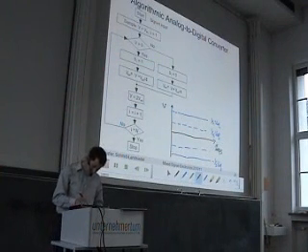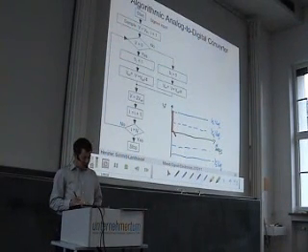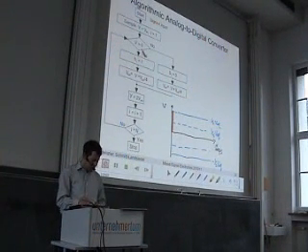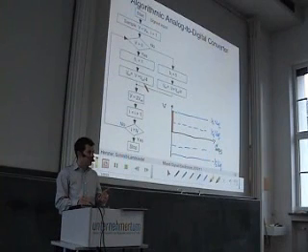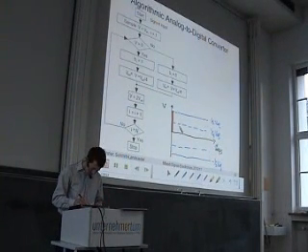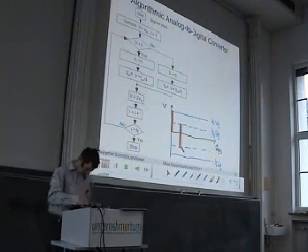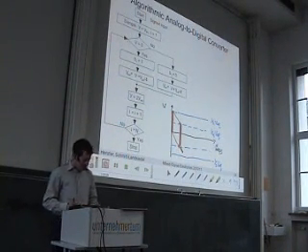Okay. All voltages that are in this range, for these voltages, we are positive. So we can say V larger than 0. Well, for the red voltages, yes. So we set the respective bit to 1. And we have to subtract Vref/4. So we go down by Vref/4. So the red voltages are transferred into this voltage. So this one goes here, this one goes here, and so on.